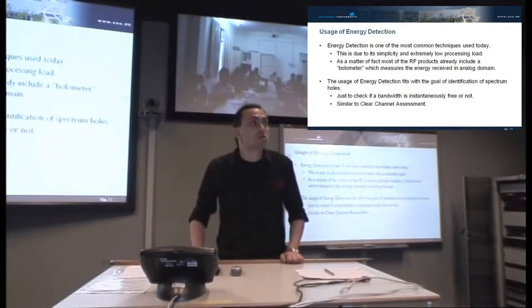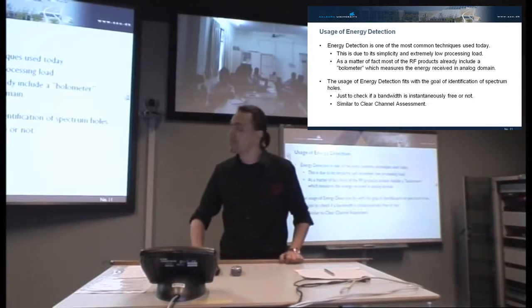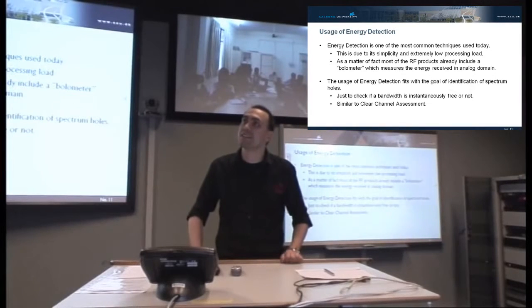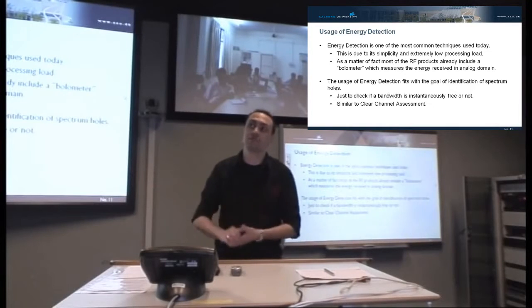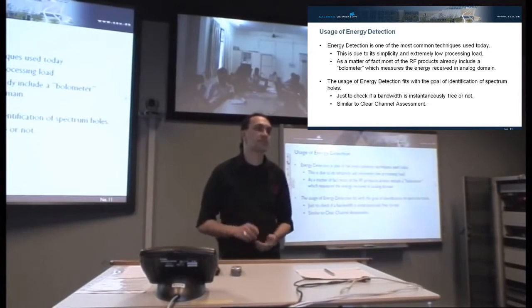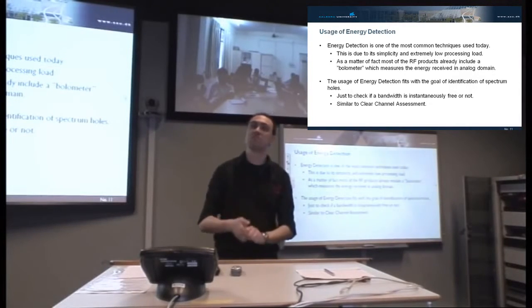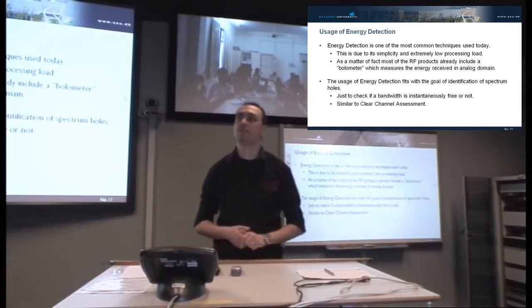And for spectrum sensing, it could be good enough. I want to detect if I have an opportunity or not. Let's assume a reasonable threshold for saying that the channel is free. If I see an energy which is below the threshold, the channel is free, let's use it. Classification is basically a threshold comparison, one if-else rule, and that's it. Done. We have our cognitive radio.